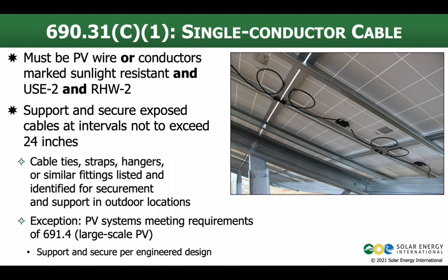They're engineered, and there's an exception that says, hey, if the supporting and securing of these single conductor cables is part of an engineered design, it's going to be stamped and sealed by a professional engineer, then that's going to suffice. We don't have to follow this 24-inch requirement. So some flexibility there on our bigger PV systems.